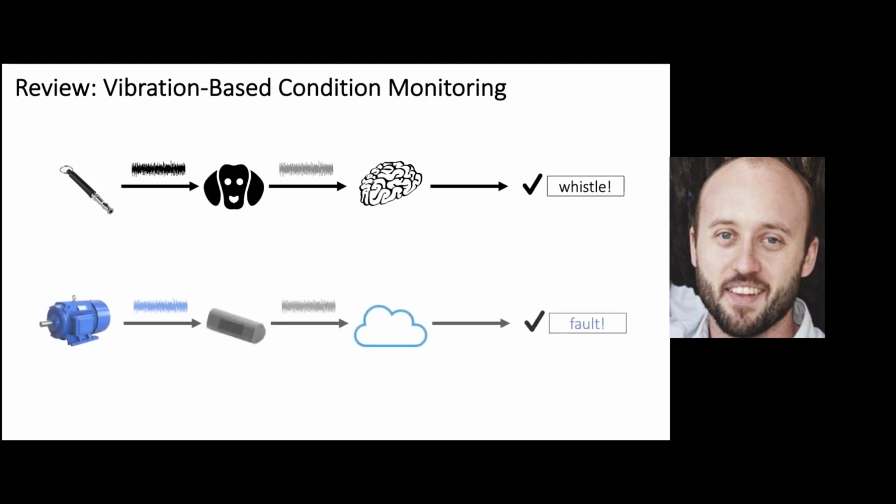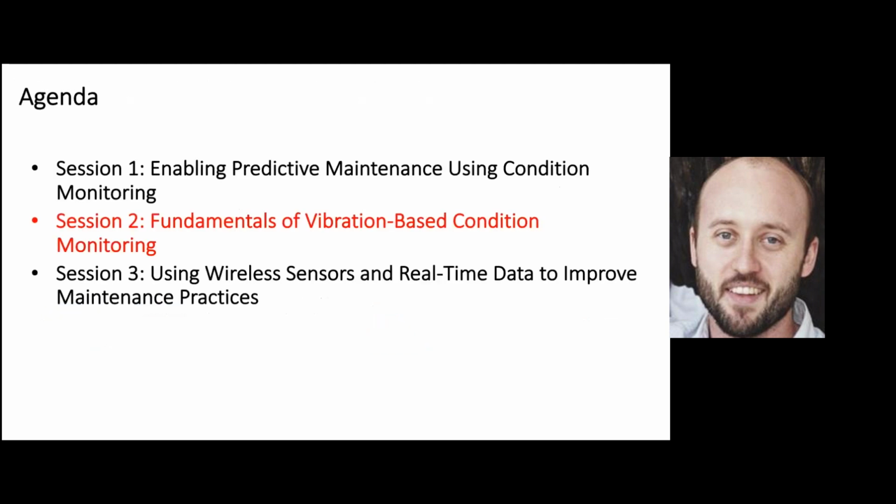And we made that analogy to vibration in rotating machinery and looking at specifications for condition monitoring hardware, with the understanding that increasing the bandwidth or the range of detectable frequencies on condition monitoring hardware is what's really going to help us to do that fault detection or diagnostics or prognostics and enable predictive maintenance.